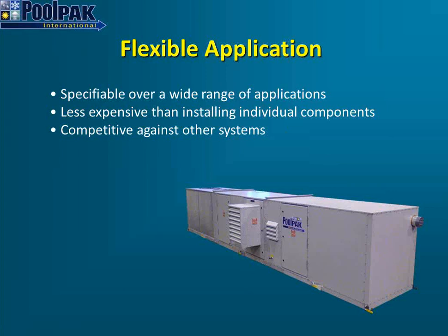It's a wide variety of applications to different pool natatoriums. Less expensive than installing the individual components, your PoolPak unit, air-cooled condenser, and other components. Less wiring, less power, no DX piping to be done, and it's competitive against other systems out there in the market. Again, the major benefits are it's a single crane lift. You get that factory quality control out in the field. You don't have any piping to do. It's run tested in the factory. And again, you're bringing factory quality control to the job site in a very, very complete, neat package.